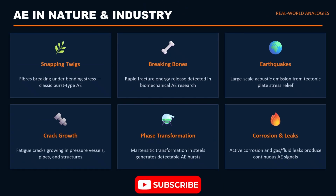Acoustic emission. When bones crack, that's acoustic emission. Even earthquakes are basically massive acoustic emissions caused by stress release inside the earth. Now in industry, exactly the same principle applies. When cracks grow inside a pressure vessel, when corrosion becomes active inside a storage tank, or when leakage occurs in piping, stress waves are generated. AE sensors detect those waves.